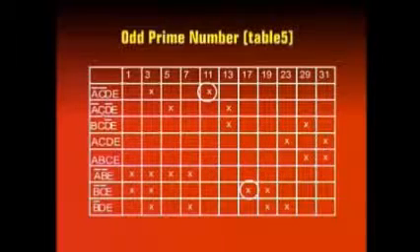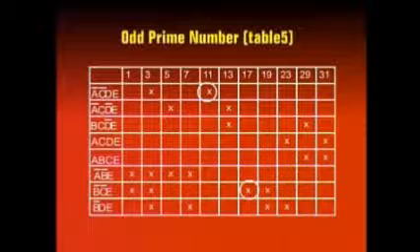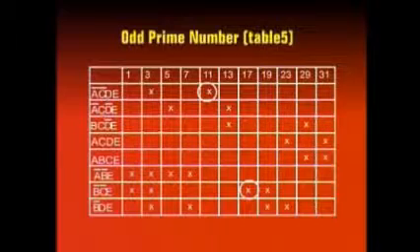The other essential implicants that have minimum number of variables and which cover all the remaining minterms are B, C, D bar, E, A, C, D, E and A bar, B bar, E. Thus, the simplified expression that represents the odd prime number in the range 0 to 31 is represented by the product terms A bar, C bar, D, E, B, C, D bar, E, A, C, D, E, A bar, B bar, E and B bar, C bar, E.